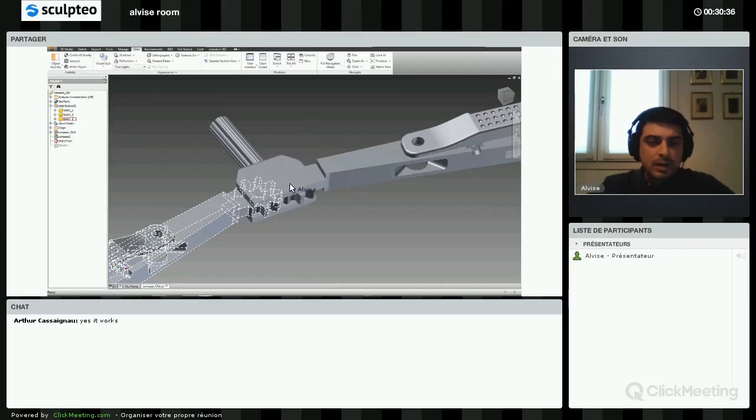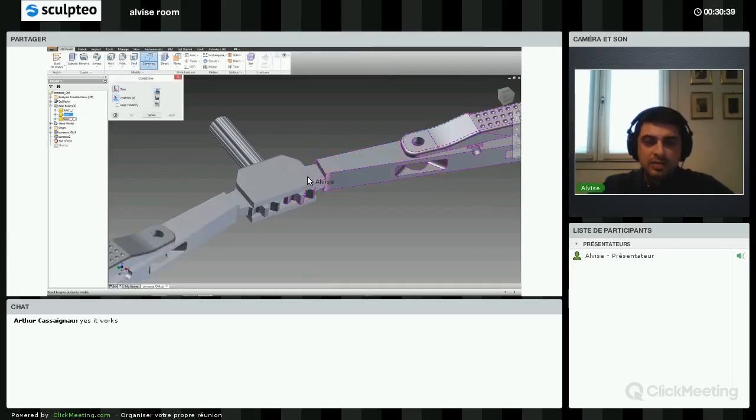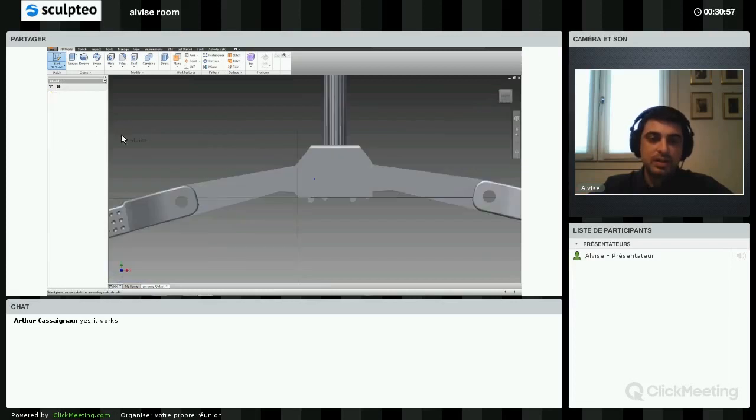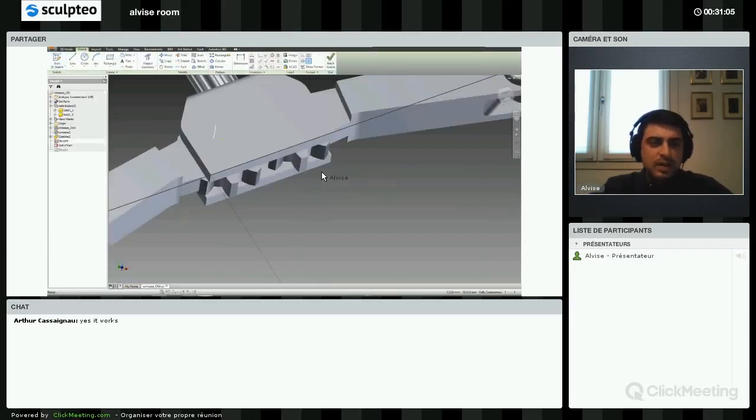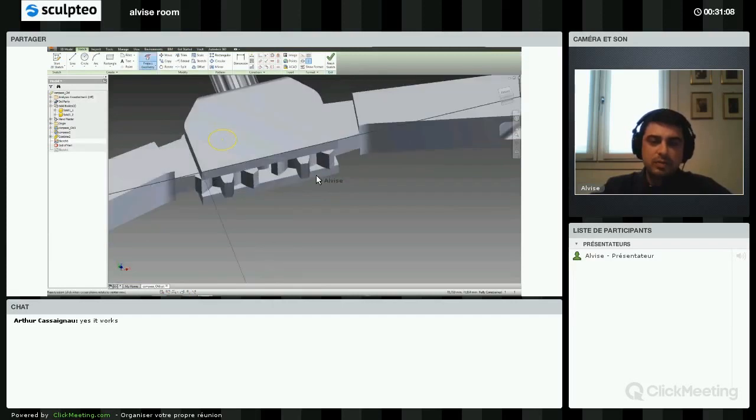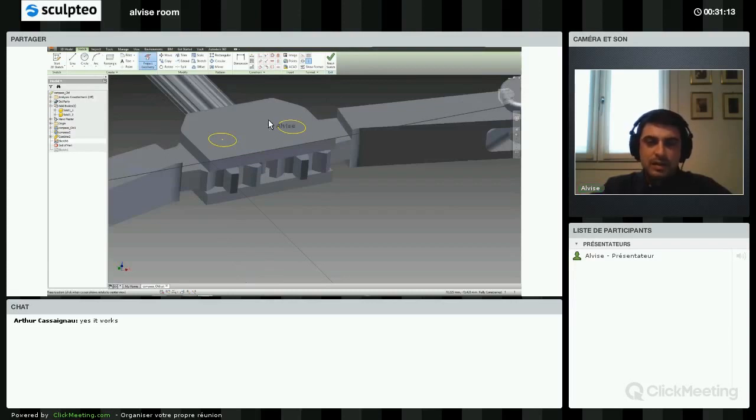So what I want to do first is project on a sketch on the top of the middle component the diameter of the circle that is now in the gears. I project these two diameters on the sketch. I will keep the visibility for that component that we're going to modify later, because we still need it in the configuration it is now.